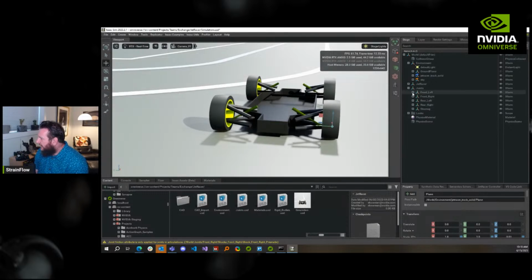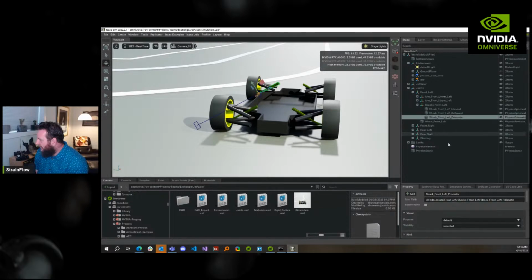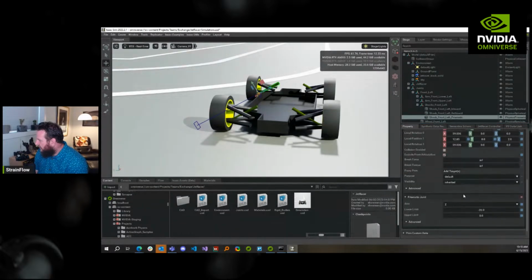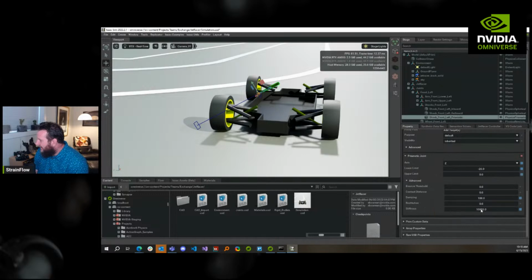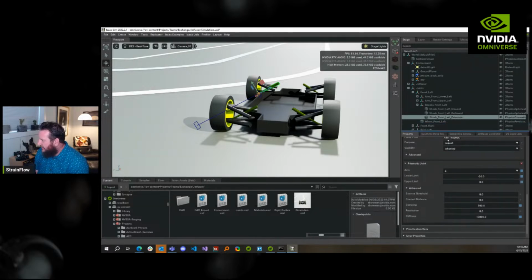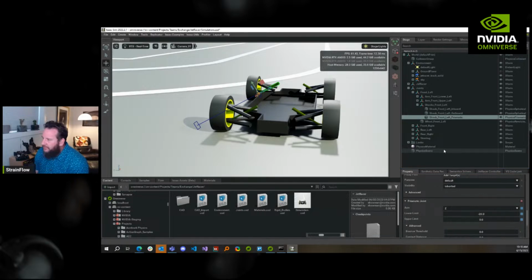Let's take a look at the shock spring rate. Just curious. I've got it at 10,000, which should be newtons per meter, from what I've read. So what does that mean? We're in millimeters here, right? We want 1 millimeter to be about 1 Newton.